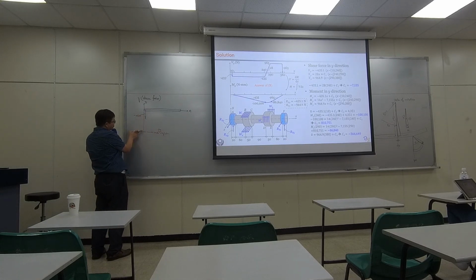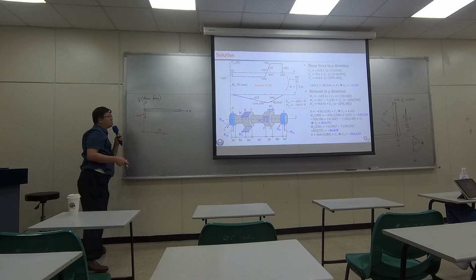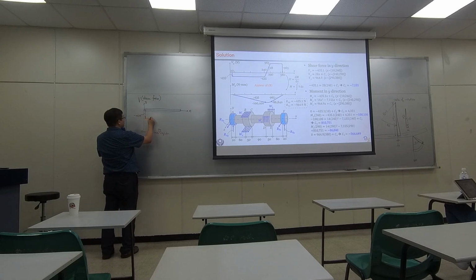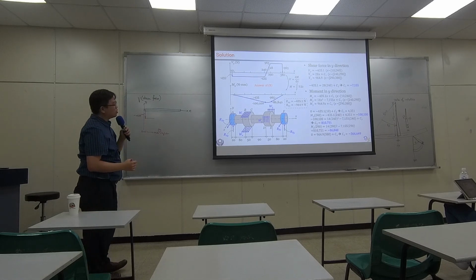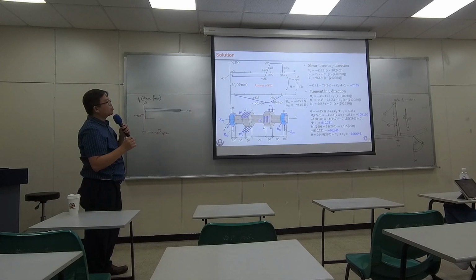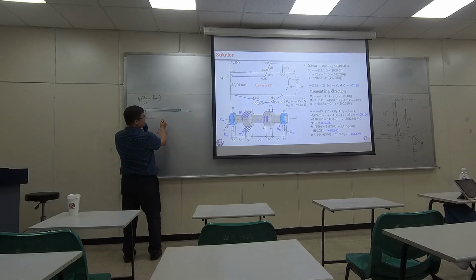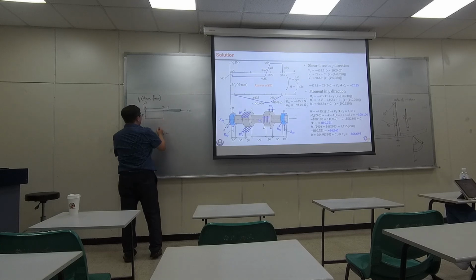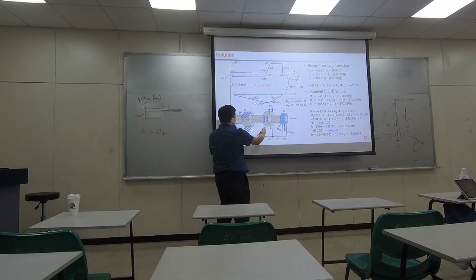So for the shear force diagram, when you walk toward right, when you meet a reaction force, an individual force, then it's pulled down up to a certain level. Then you keep on walking, so your shear force remains the same until you see distributed loads. So over here, this is position A, this is position B, position E. Up to here, up to position D, that is where you see the distributed loads.